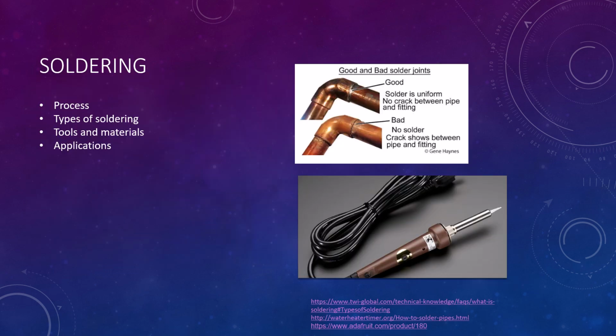Soldering is the process of joining two or more metal components together by melting a filler metal, called solder, into the joint. The solder cools and hardens, creating a solid electrical and mechanical connection. A good solder will have a shiny and smooth finish, which indicates proper heating. The joint should not move during cooling because this can create cold joints.